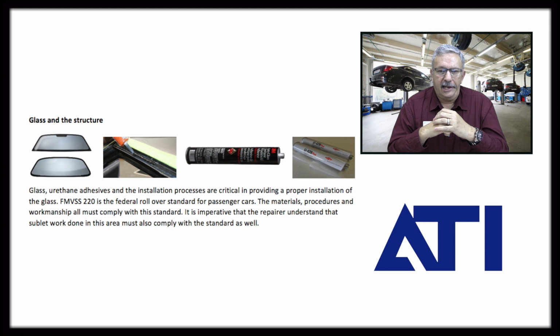The area where that adhesive is going to be placed, once the vehicle is painted, needs to be taped off so that you have bare metal there, so that when the urethane primer is put on, it is going on bare metal. That is a requirement of most of the adhesive manufacturers. You cannot put the urethane over fresh paint.